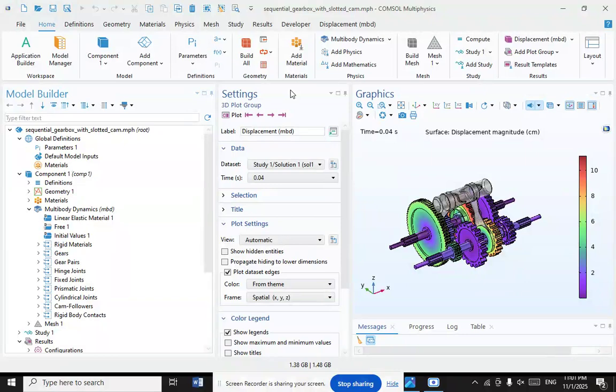Once these speeds are equalized, the dog clutch can engage and thus the new gear is now in use. In a modern gearbox, the action of all of these components is smooth and fast. It is hardly noticed. Many transmissions don't include synchromesh on the reverse gear. See reverse gear section below.